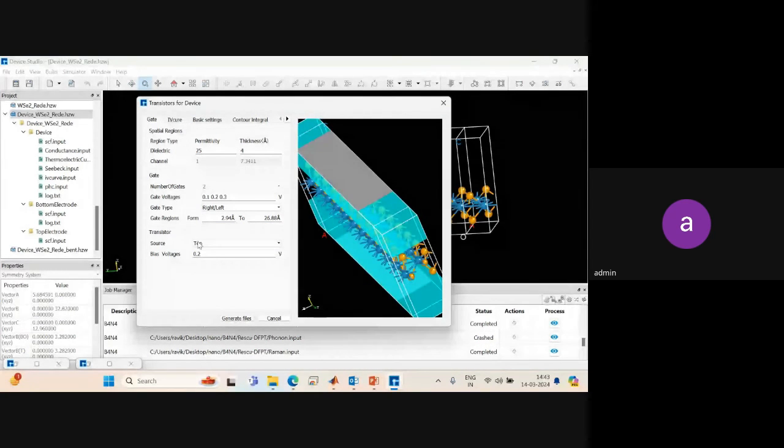And this is for a transistor, where your transistor may be on the top side or bottom side. But apply some bias voltage, source voltage, to plot the ID-VD characteristics. The source voltage is also required, the VD value. So 0.2, 0.4, 0.6, let's suppose you want to apply. And here you want to apply 0.1, 0.2, 0.3, 0.4, 0.5, like that. We can change these values according to our need. On different devices, we can apply it.